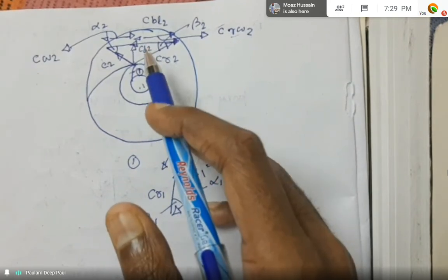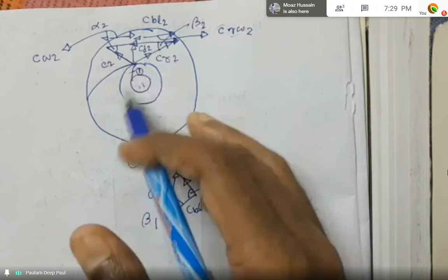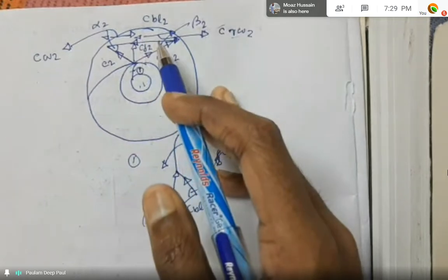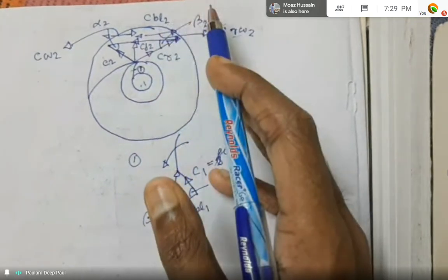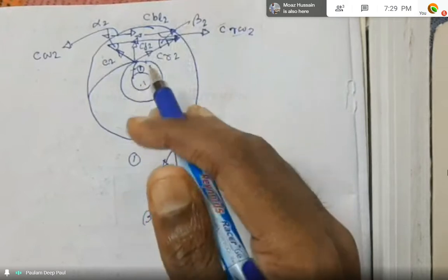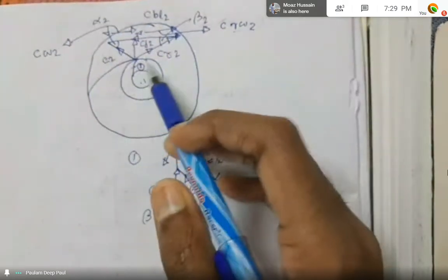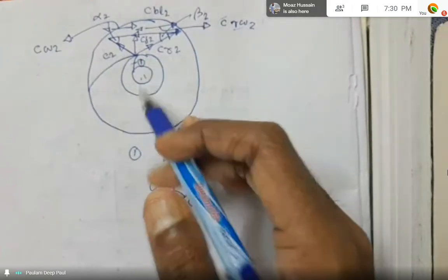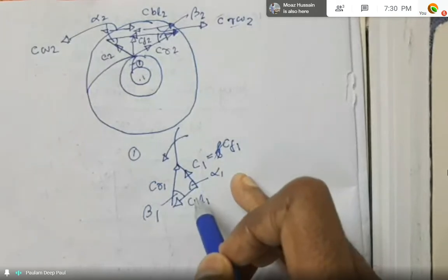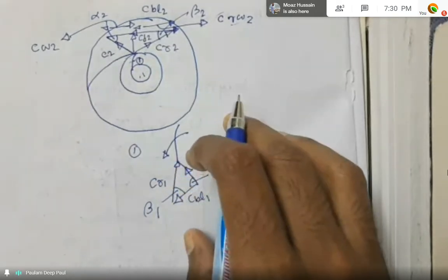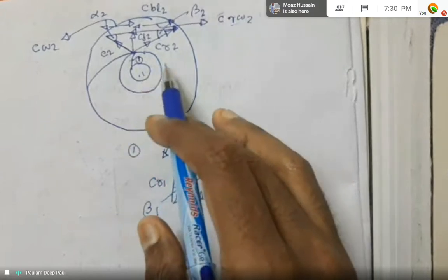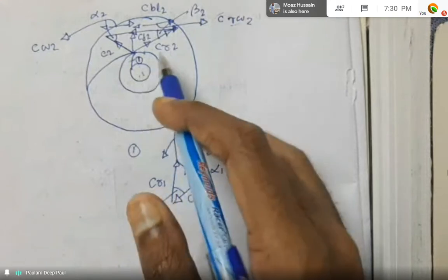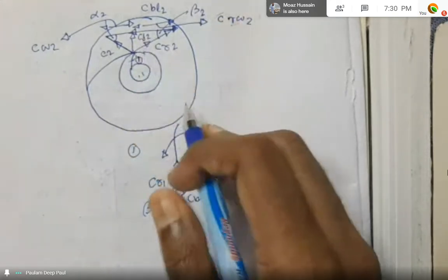The impeller transfers the energy of the drive that is already driving the impeller to the air, causing a rise in both static pressure and temperature, and an increase in velocity. With the increase in pressure and temperature and velocity and everything, and not to forget the angles that we have already drawn here, just take that into consideration. So the work done on the compressor, the work input, should be equal to the rise in the total temperature, that is point one.